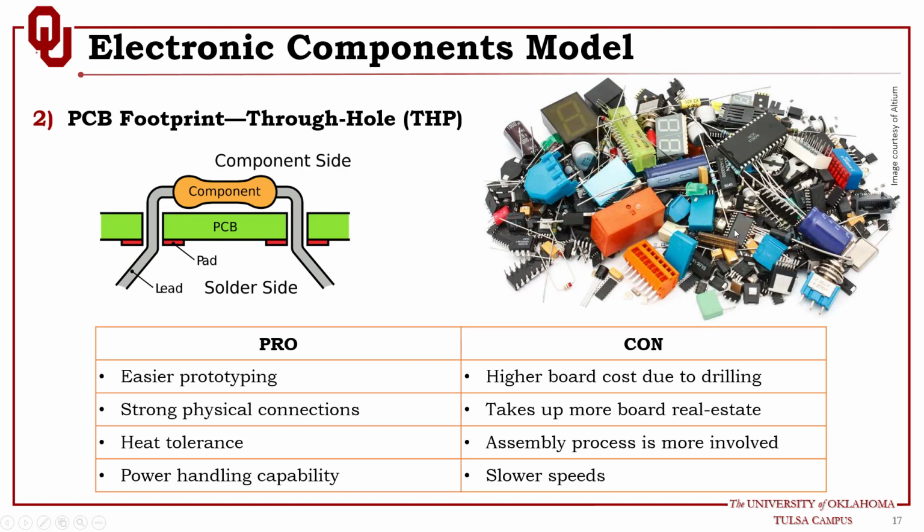These all are leaded components, as you can see. Oh, we have some through SMT components, but these pins, all these are leaded components. You need to make a hole in the PCB to insert the component through the hole or the drill, and then you have a pad where you have the soldering joint to solder the component with the PCB.